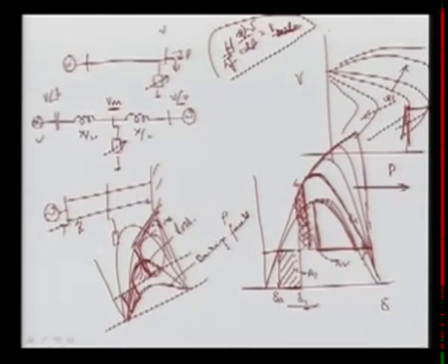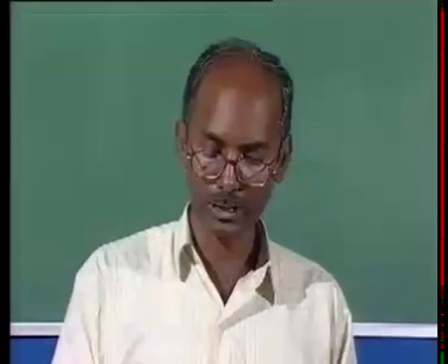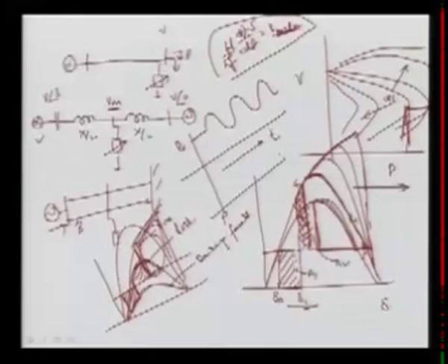So what happens, the power swing here is normally of this characteristic. Let's suppose the power is oscillating, and it started oscillating here. This was your P naught, and this is with respect to time. So this is oscillating. Now what we can do, if we can have some mechanism for reactive power support from this point, means if it is oscillating we can inject more reactive power in the system, and if it is underdamped, then we can go for this.